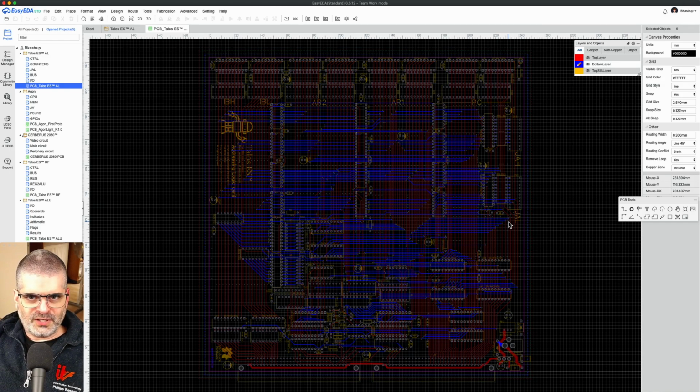It's better that it be a snake than a crab, because it reduces reflections. But I couldn't do everything as a snake. For instance, you can see this signal here. There is one branch. If you go to the next one, there are 2 branches on this net. The next one, 1 branch, 2 branches, 1 branch. So you get the picture.